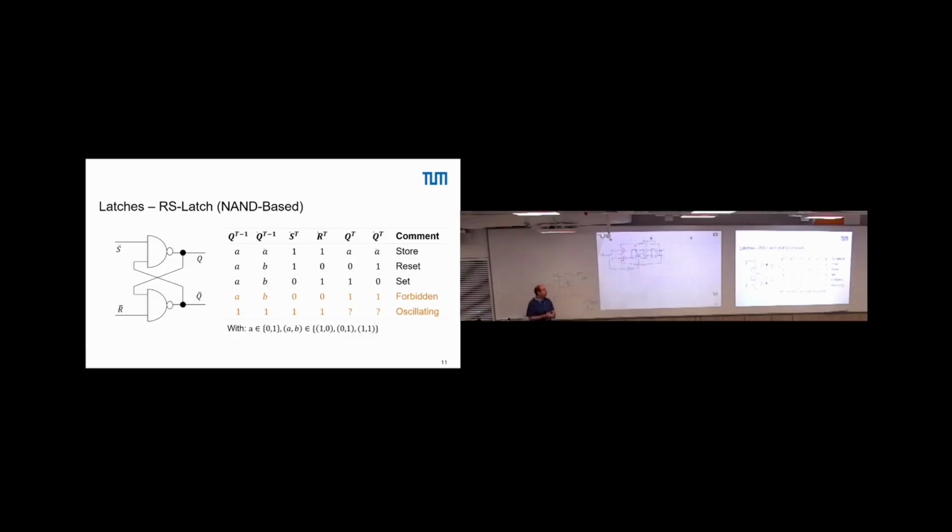Nevertheless, if we build the thing like this and respect the setup and hold times, then we do not have these metastability issues here anymore. And we have something that is really clear on the, in that case, falling, in general, rising or falling edge.